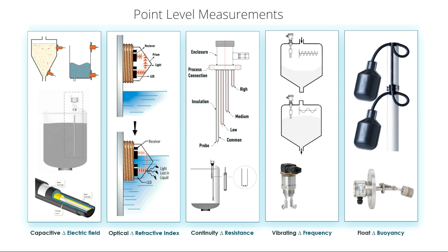Another one, which is also a common type, is the tuning fork based level switching. They use vibrating tongues to measure the level of a liquid. The level is detected by the change in frequency. Okay, and again we have a sensing circuit that will detect this and give a signal appropriately.